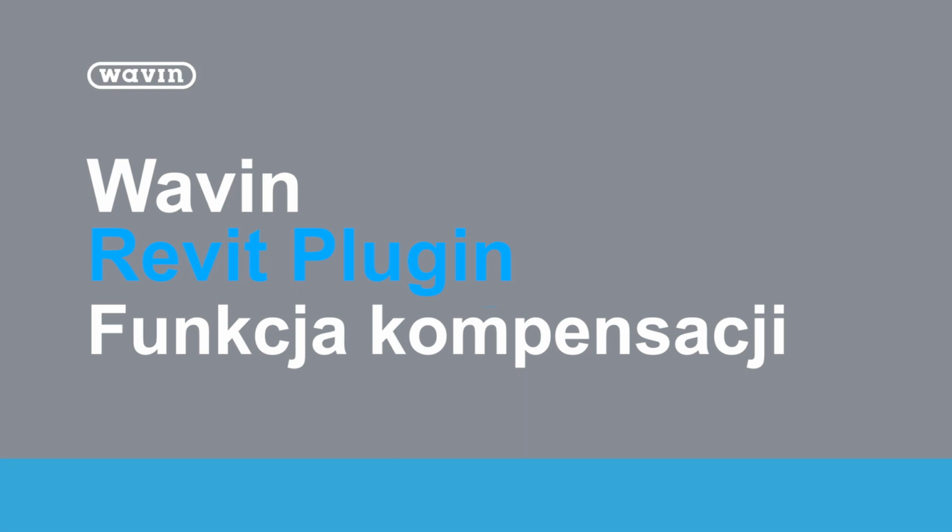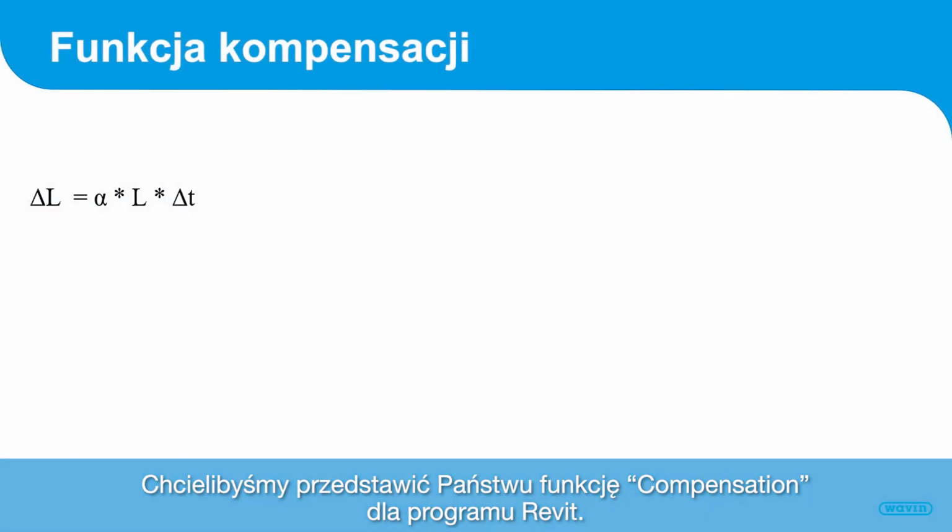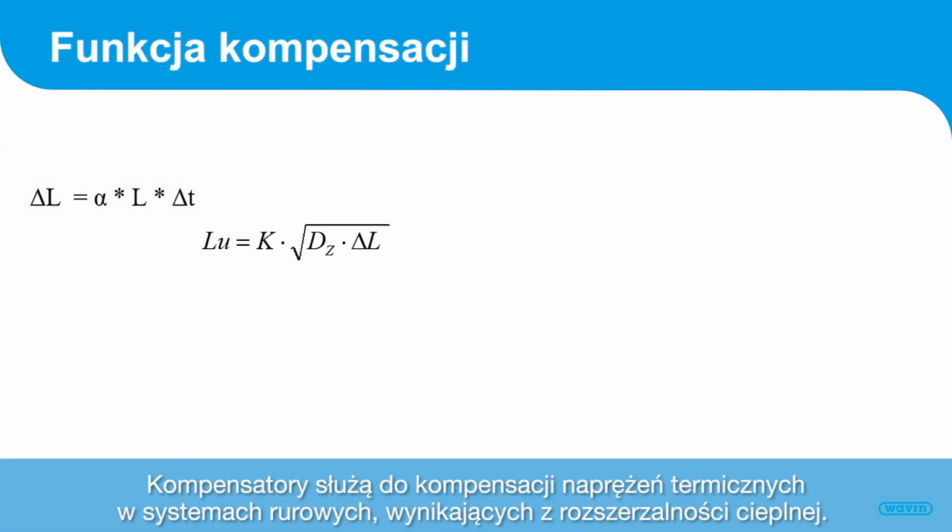Wavin plugin for Revit. Compensation feature. We'd like to present the compensation feature for Revit. Compensators are used to compensate for thermal stress in pipe systems resulting from thermal expansion.